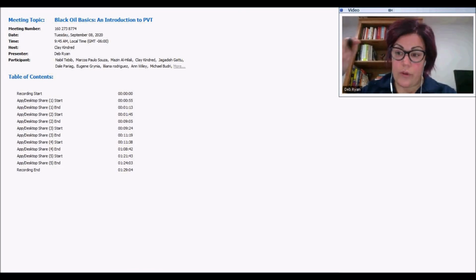And it's also in that picture I showed, with the very light gas condensate at the surface at the top of the reservoir going all the way down to an oil rim at the bottom. That is a density impact throughout that reservoir because of how thick it was, because those heavier components want to be at the bottom and the lighter components want to be at the top of that column. So density can vary throughout the reservoir, and in those kinds of situations, we would need to understand the gas oil ratio impacts and the way that reservoir density is going to change with time throughout the reservoir. That's quite an extreme case in that particular scenario.